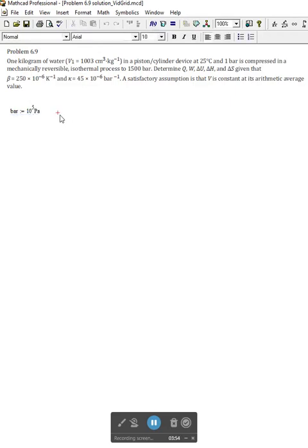Remember, if I want to do Greek letters, and I try to keep the nomenclature as similar as possible to what we are using in the book, the lowercase beta is lowercase b, and then I hit Control G for Greek, and that changes it to beta. And when I assign a value, remember you use colon, and so that'll be Shift colon. That assigns a value. That's MathCAD's little sign for assigning a value.